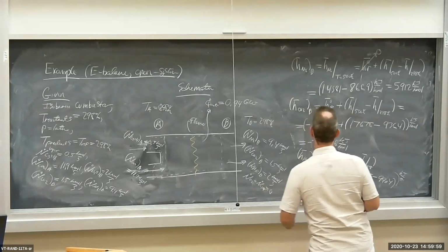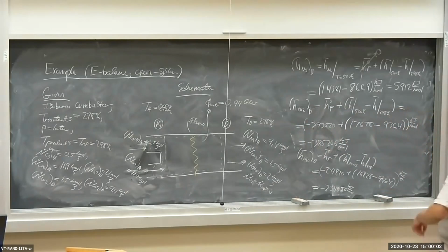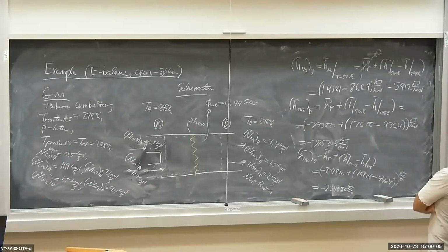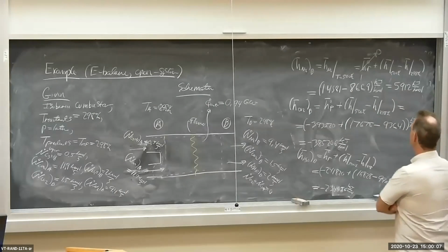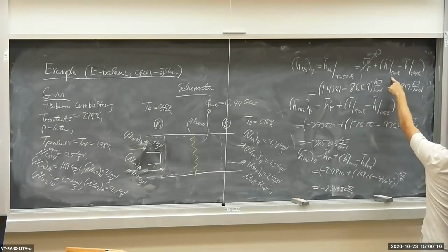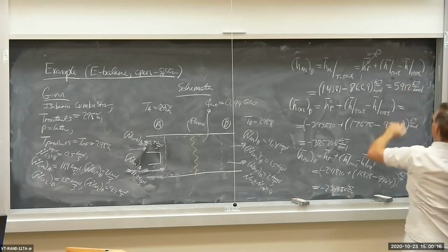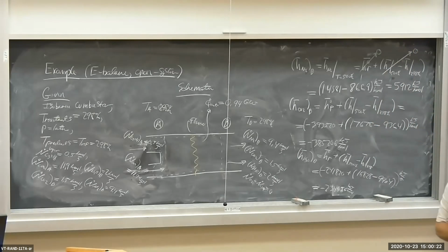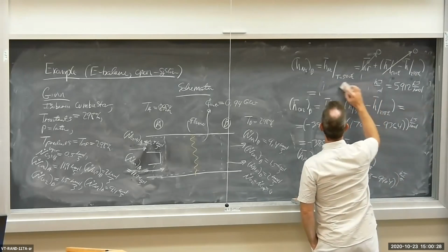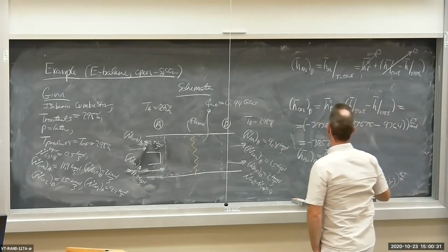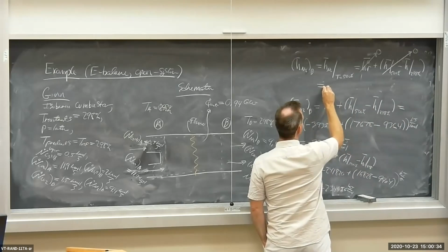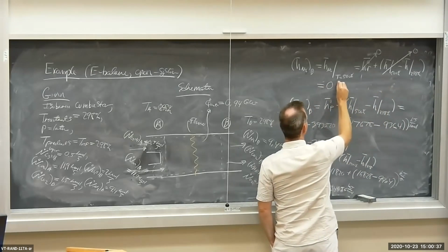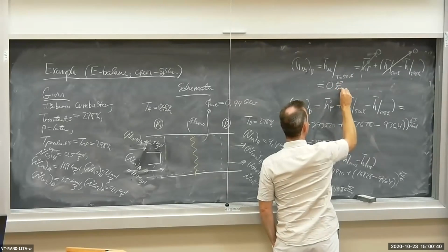And therefore, the enthalpies we have here are a little different. Let's see here for the N2 at the outlet. The outlet temperature is not 500 anymore, it's 298. So the delta H goes to 0 in the enthalpy term for nitrogen, so this is now gone. So we have specific enthalpy, H bar for the nitrogen at the outlet, is 0 plus 0, so 0 kilojoules per kilomole.